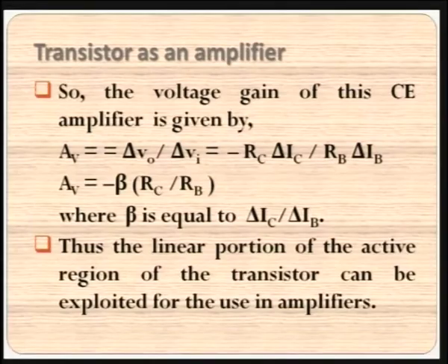It is time for us to see how to keep this transistor in the active region. It should not be driven to the extremes, that is the saturation and cutoff region. We have to maintain it in the active region to enable the amplifier to work properly. How is it done? For that, we need to consider a line called the load line. We have to draw a load line on the output characteristics curve, and then we have to fix a point. Any variation that is happening should happen with respect to that particular point. That point is called the Q point.